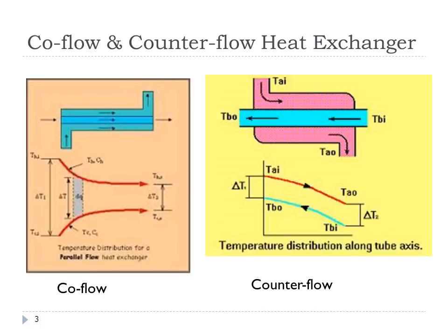In the counterflow, the flows are flowing in opposite directions. So what happens is there is a temperature gradient on one side, and then throughout the heat exchanger there's a temperature gradient. And you can see in the counterflow case, the temperature difference between the hot and the cold side stays normally fairly constant.